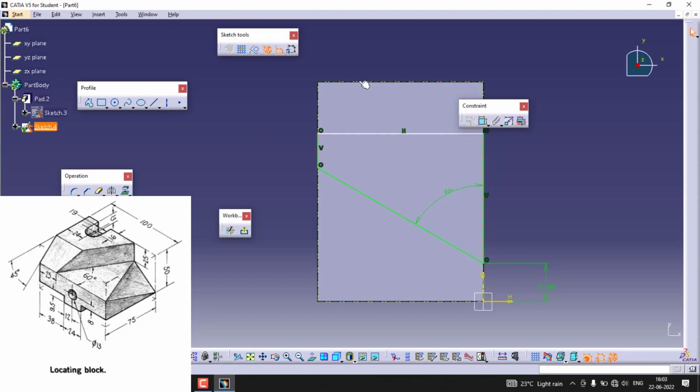What to do with this? Yeah, I could say it is very complicated to select the edge. So you can simply remove this as I said. So you can select all the edges as a reference and make it for construction like this. Now this will help you to snap the edges very easily. Could see.